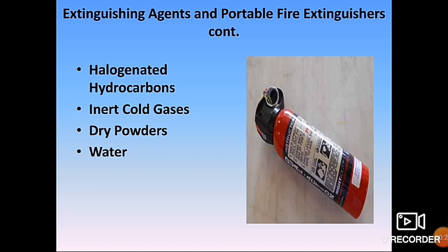CO2 has been used for many years to extinguish flammable fluid fires and fires involving electrical equipment. It is non-combustible and does not react with most substances. It provides its own pressure for discharge from the storage vessels, except in extremely cold climates where a booster charge of nitrogen may be added to winterize the system.